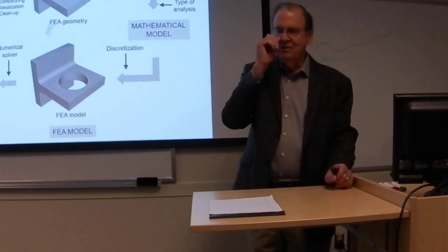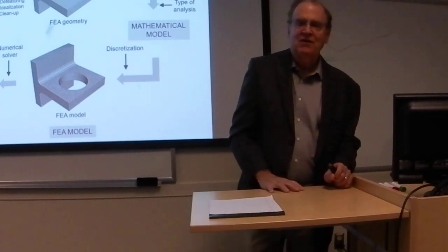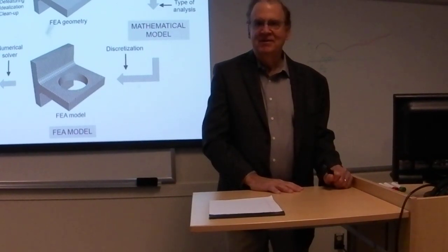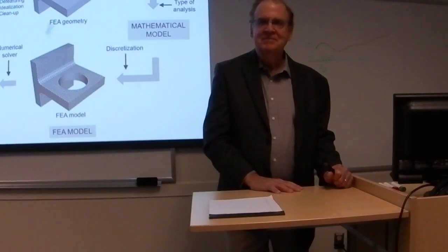And did you always do a mesh refinement? Not always. You usually do at least some kind of mesh study to see if your original mesh was of decent quality. If it was, it'll always spit out results, but it won't always be your right results. So you generally change a few parameters and rerun it and see how much it's changing. If you do some refinement or a coarser mesh and see if you get similar results, then go with the one that's less computationally heavy.